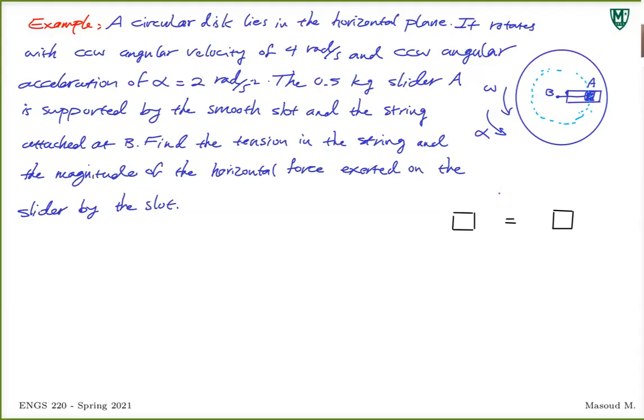So since it's going on a circular path, I can use tangent normal coordinate system. You will see later on you can even use polar coordinate system. In this case, let's just use normal tangential, whatever you want to refer to it. So I'll take this and this. Remember, tangent is in the direction of the motion, positive, right? So I take this as AT. Normal from the point concave. If you think about your curve, and this is the concave, this is going to be the direction of the normal. Part of it, that was your quiz as well.